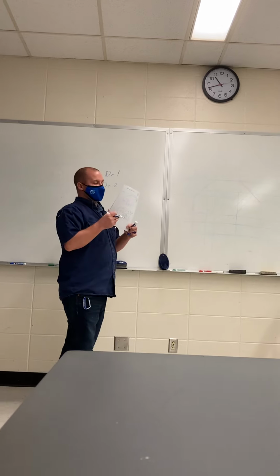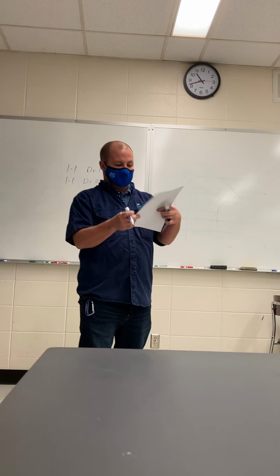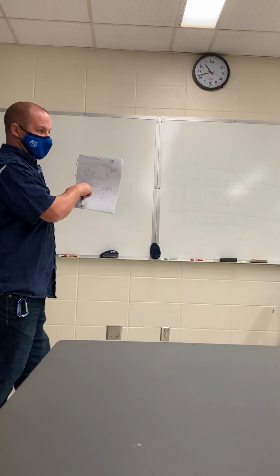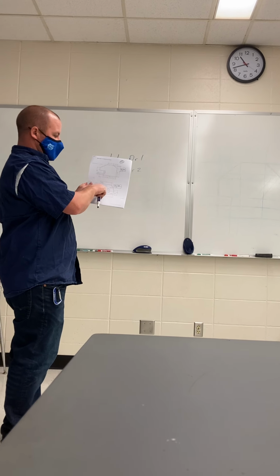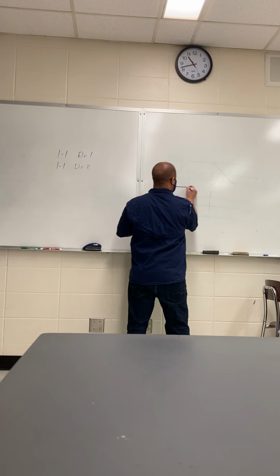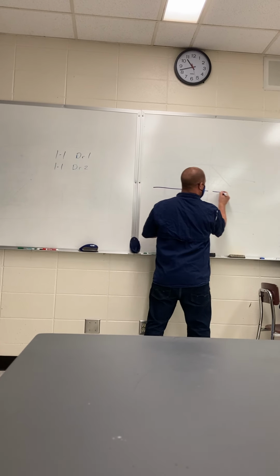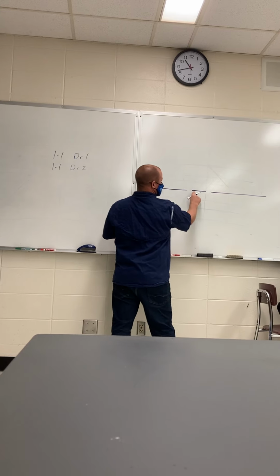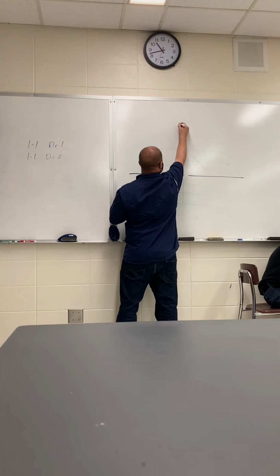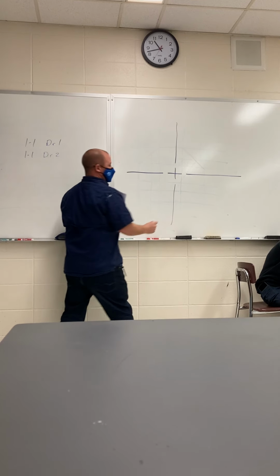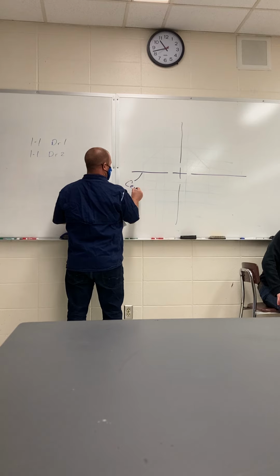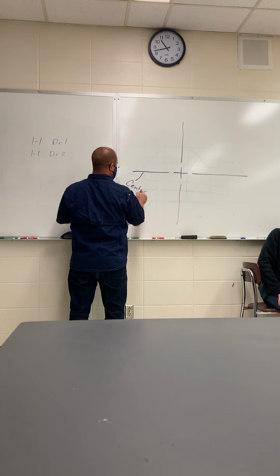So, this is the first time that I'm bringing this up to you. But look in the center of those circles in drawing 2 on 1-1. You'll see a line, hang with me, that looks like this. Long dash, short dash, long dash. You'll see another one that intersects it. Long dash, and a short dash in the middle. These are called center lines.